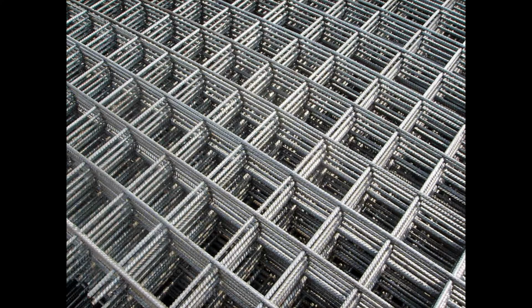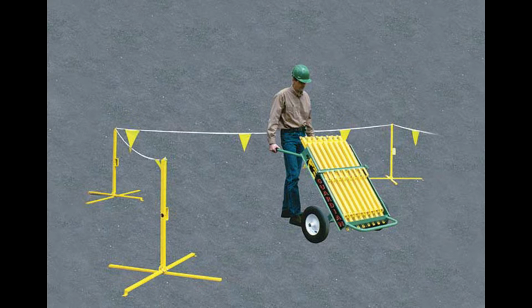Formwork and reinforcing steel. On a job site that requires formwork or reinforcing steel work 6 feet or above lower levels, the following fall protection systems will be used to protect our employees. Number 1, personal fall arrest or positioning device. Ramps, runways, or other walkways. We equip all ramps, runways, or other walkways with guardrails when employees are subject to falling 6 feet or more to lower levels.